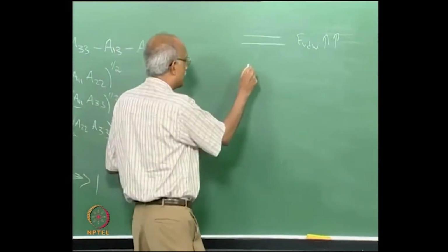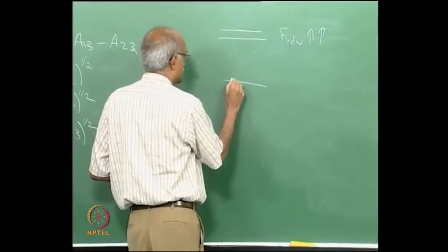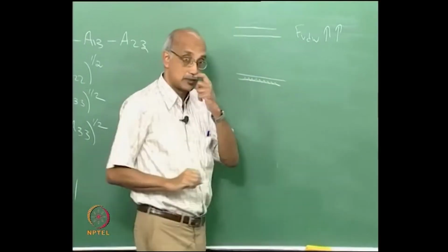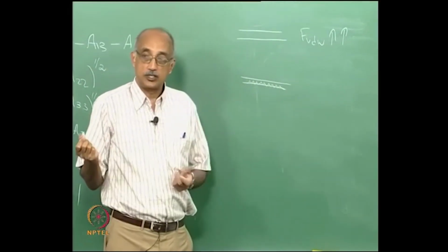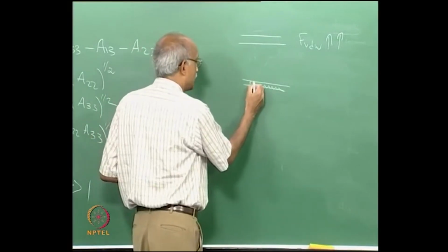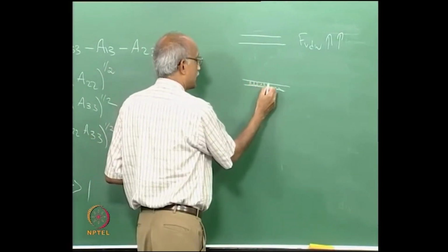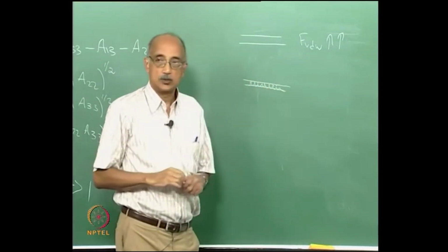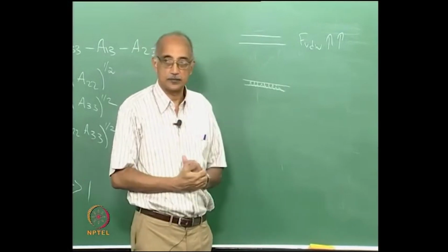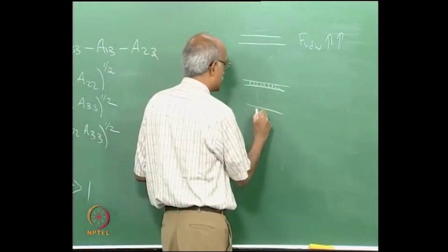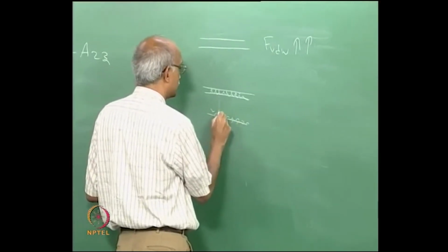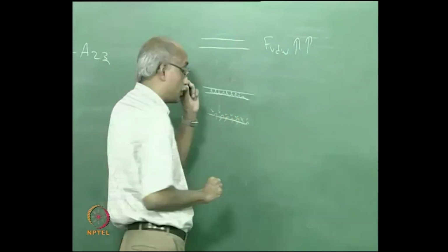But supposing now you roughen the bottom surface so that you introduce some asperity and now the top surface comes down, the forces are going to be reduced, right? Because the effective area of contact is now only the peaks of the asperities, and so it virtually halves the area that's available for contact. Now if the top surface is also rough, then what happens?